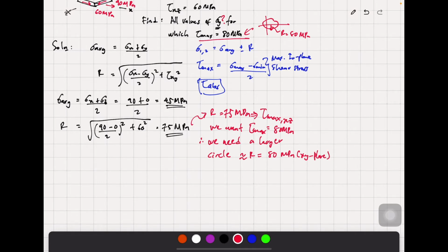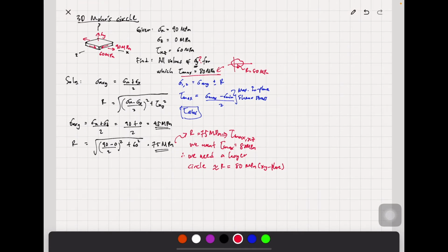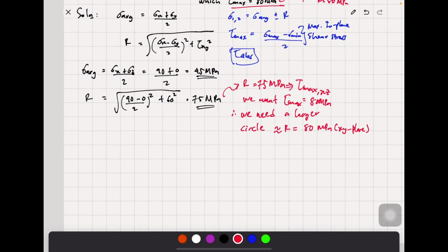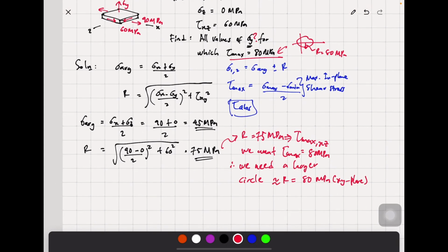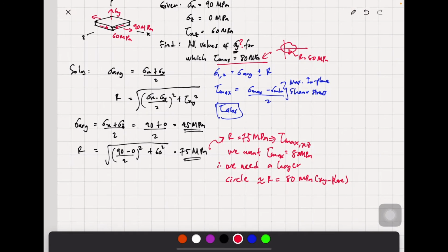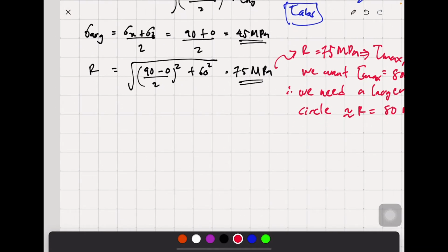All right, I'm talking about the plane right now, so you're going to see that on the Mohr circle afterwards. But we're going to do some assumptions over here because there are two, right? Sigma 1 and sigma 2, the principal stresses, maximum and minimum. So sigma 1 equals 45 plus 75. This is one of the conditions, saying that the major stress for the system is 120 megapascal.